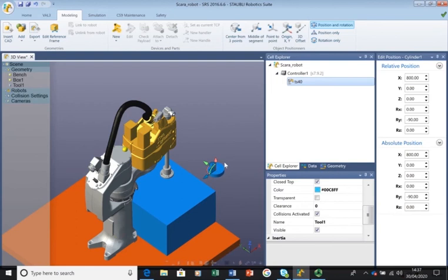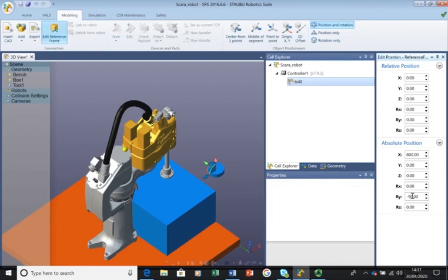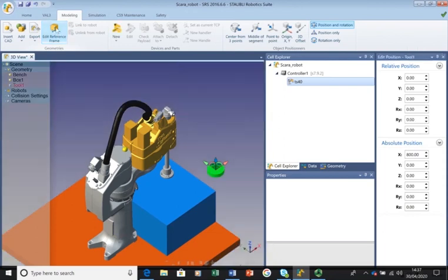That's this coordinate system within there, and it's come up with this. So it's editing the reference frame, and I've rotated it 90 degrees. And let's just change it back, and that's okay now. One thing with editing the reference frame, it's the same as clicking this icon along the top in the model, the fourth one along, edit reference frame, but it's a toggle. It's currently still on, so if I did any more work, I'd really mess this up, and you can accidentally move this reference frame all the way around the room, and you regret it later on. So do remember to switch it off.